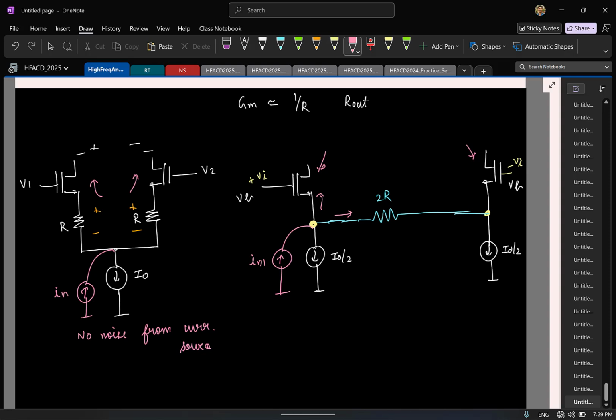Noise current source, only to the one particular noise, not by two from other. Yeah, same, it's not the same noise. I mean, again, remember that if you have two resistors or two current sources of the same value, the noise power spectral density is equal, but the noise is completely uncorrelated. Right? I mean, again, you can have two batsmen having the same batting average, doesn't mean the batsmen are equal. A property of the signal is equal, but doesn't mean the signals themselves are equal. Right?